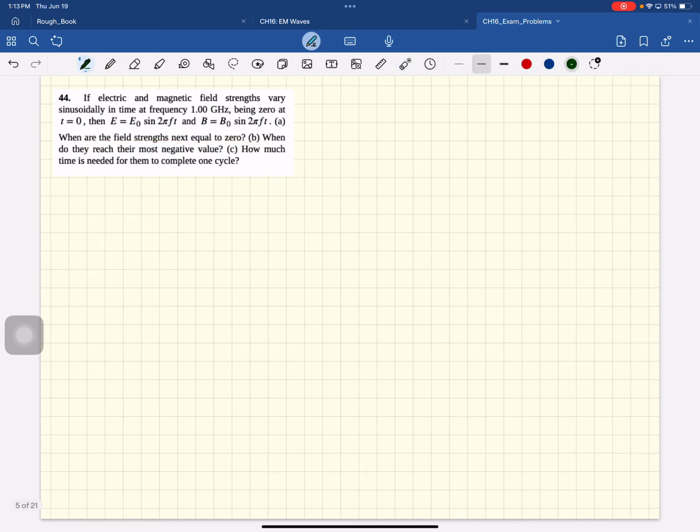Okay, so here's the wave, okay, so E is 0 here, it'll be 0 there, and this is one period, so half the period, it'll be 0 at T by 2 next. T by 2 is, T is 1 over frequency, by 2, and so frequency is, they give you frequency is 1 gigahertz.